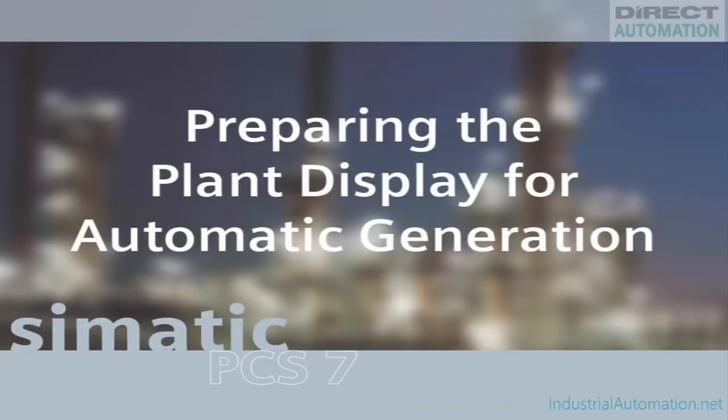In this sequence, we're going to show you how SIMATIC PCS7 automatically populates process graphics with symbols which are pre-linked to function blocks in the controller configuration. Based on the controller configuration, PCS7 can automatically create symbols which allow the operator to control and monitor CFC and SFC charts from process pictures.